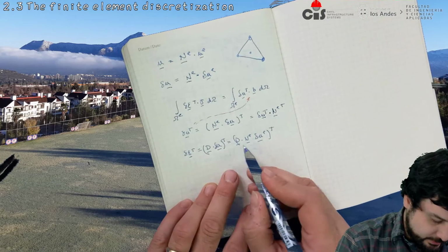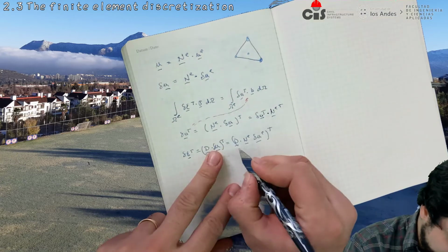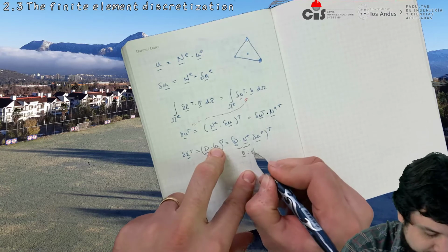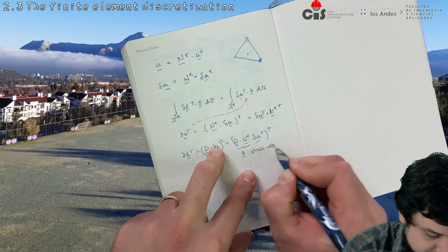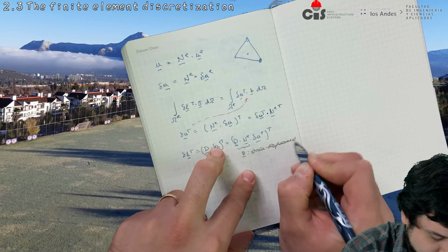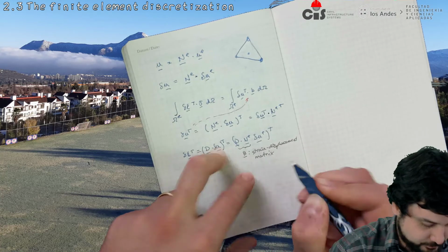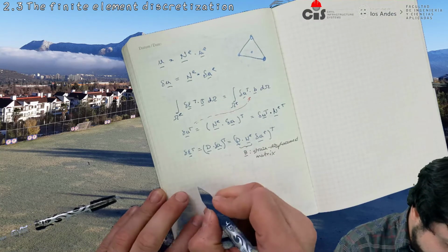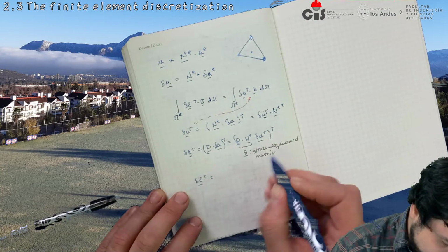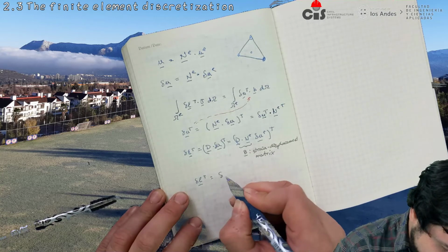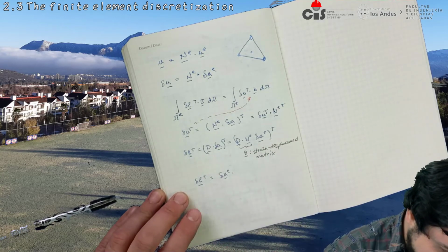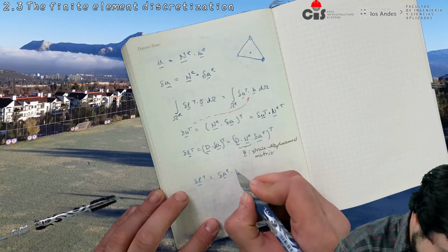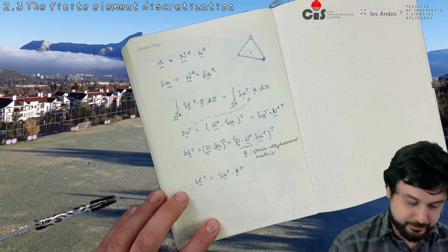And this over here we're going to call B, it's formally called the strain displacement matrix. Okay, so we continue with this. So delta epsilon transpose, if we work everything out, it's going to be delta UE times B transpose, like this.